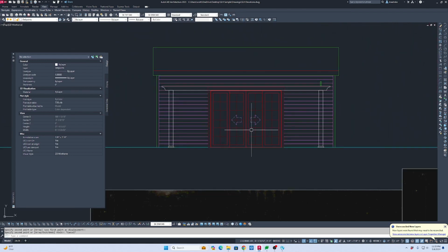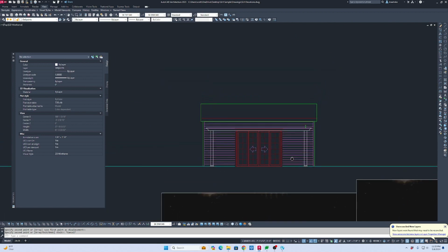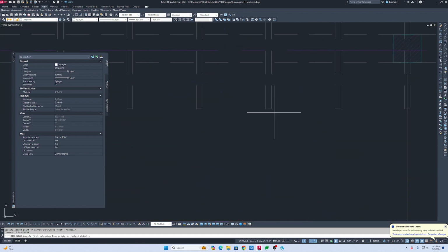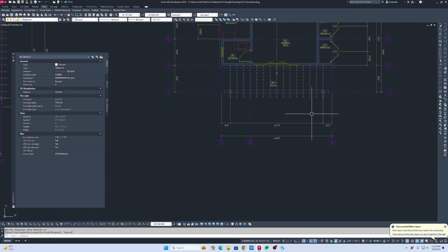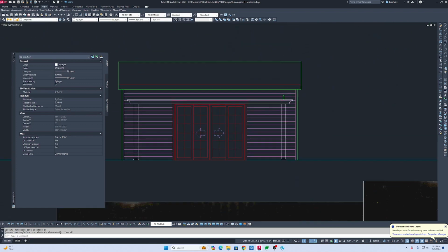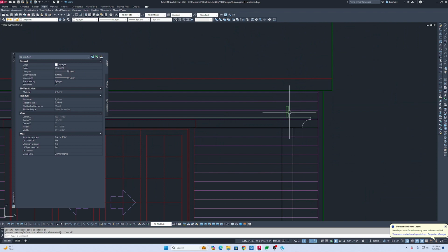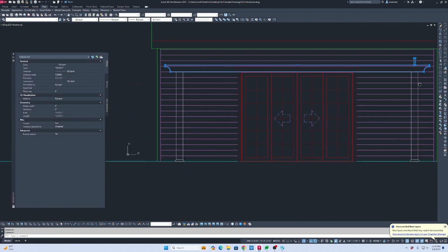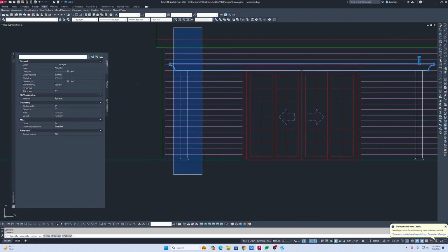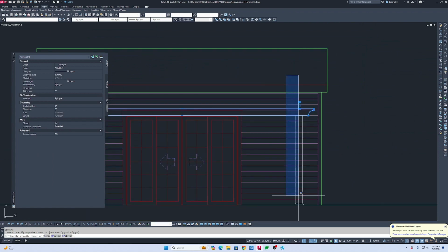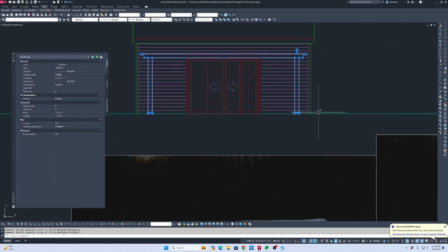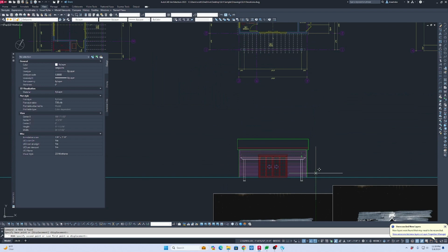So now one of the things I do with the, I gotta draw the tops. How big are these? These are 18 inches on center. Perfect. So let me copy these out of here first so I don't have to deal with the other items. Let's move this up about 10 feet.